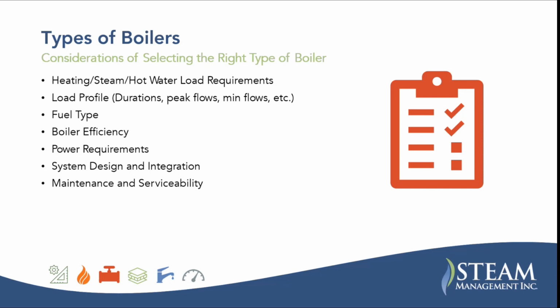Adam asked, how is corrosion in the boiler typically mitigated in a condensing boiler when incoming feed water is cold, so dissolved oxygen is generally high? That is a good question, because a lot of these boilers are for heating applications. You're usually not using a particularly sophisticated water treatment system.